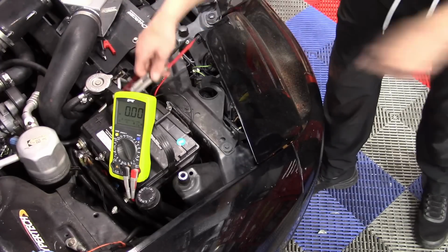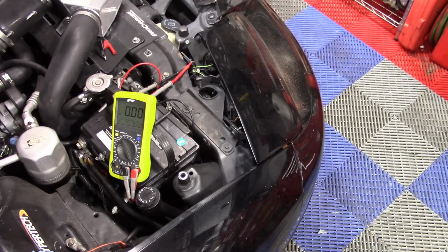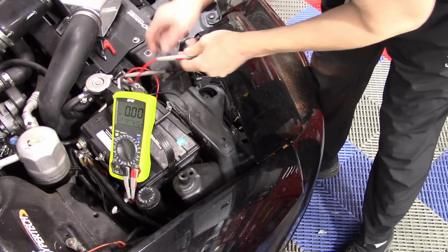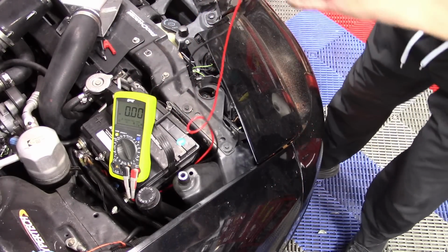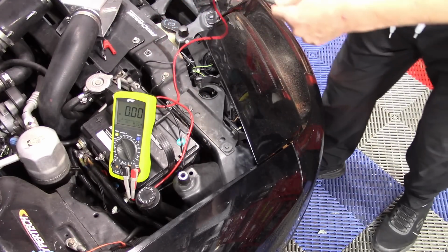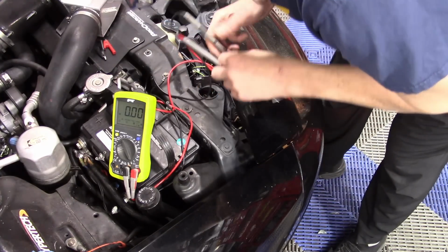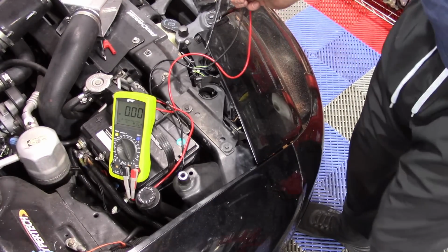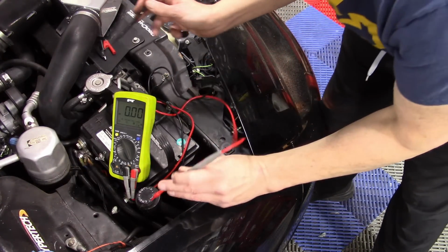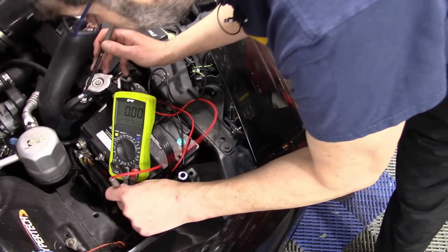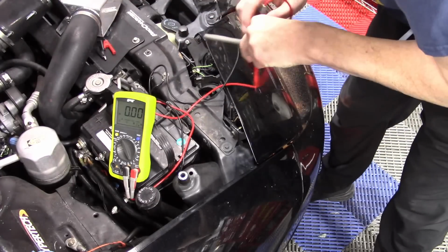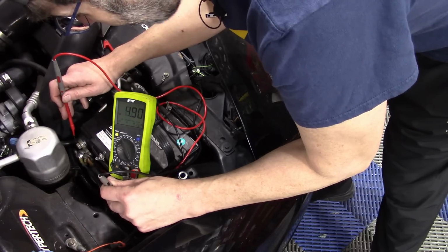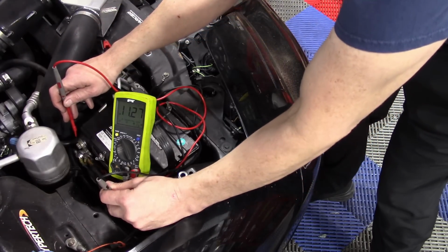All right, the other direction, let me just reread this. Measure the ground side voltage drop. First of all, do we have a voltage drop problem on our wiring? One of the things I'm a little worried about is that the voltage we measured at the bulb is actually pretty different than our source voltage, and it really probably shouldn't be that different. So I'm going to measure my battery voltage at my positive and negative directly from the battery. We see we have 11.27.